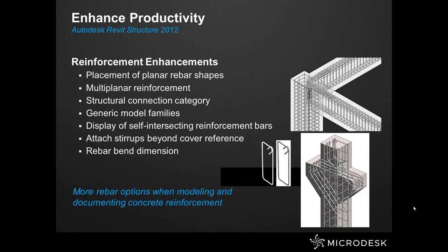There are 3 modes for placing planar rebar. Previously, the user had to choose between 2, working parallel to work plane and perpendicular to work plane. In this release, the perpendicular mode is divided into 2 separate modes, perpendicular to work plane and parallel to cover, and perpendicular to work plane and perpendicular to cover.